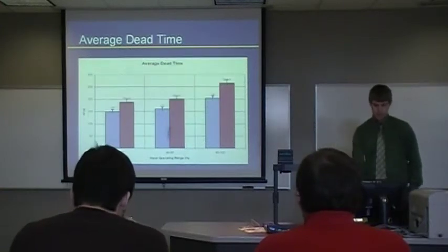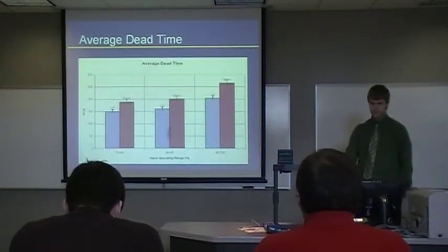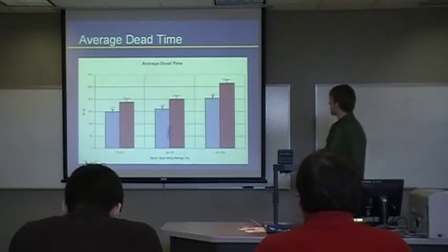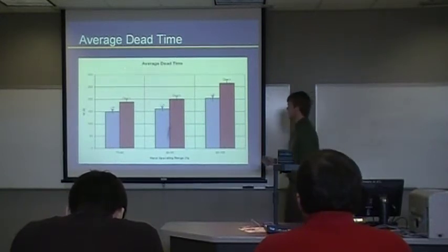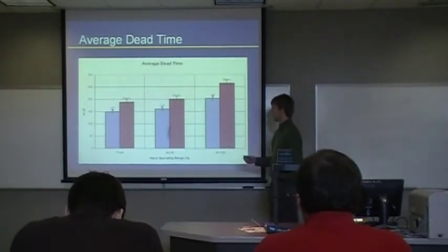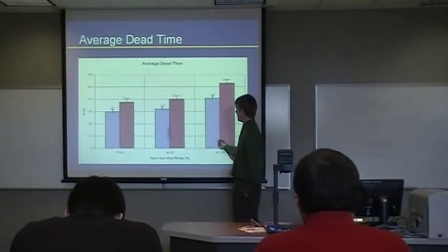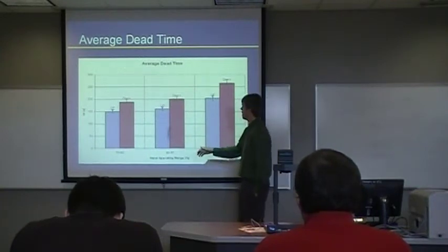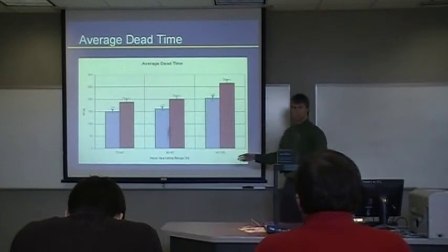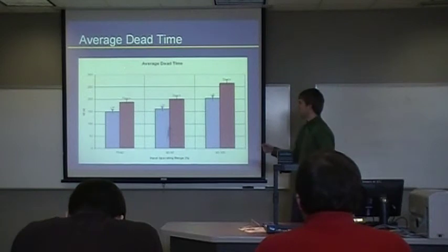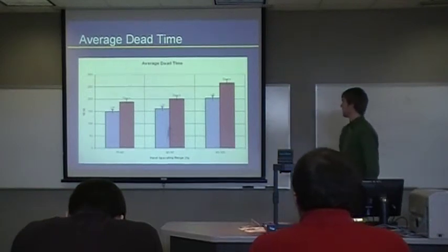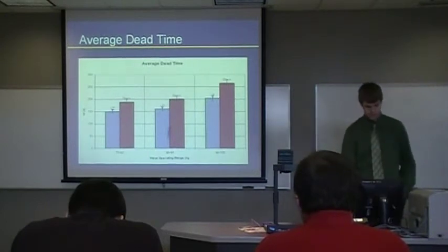The dead time, as you can see, increased as the input increased, which was opposite from what you would expect, as it took longer for the pump to respond as you increase 70 to 80, 80 to 90, 90 to 100, and follow the same trend. It was just backwards from what we expected. You expected that as you increase the motor input it would actually fill up quicker. It just took longer to respond is what we found. On the way up and down, it follows the same trend for all 3 input ranges.